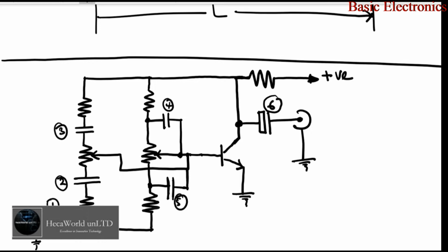These are coupling capacitors. So we're coupling one section to another, or 2 sections together. With this capacitor, we couple the AC components of both circuits or both sections, but it will isolate the DC conditions. So the power supply I have for this tone circuit will not interfere with the power supply of the subsequent circuits, whether it is the mixer or the power amplifier, but the AC conditions will interact.